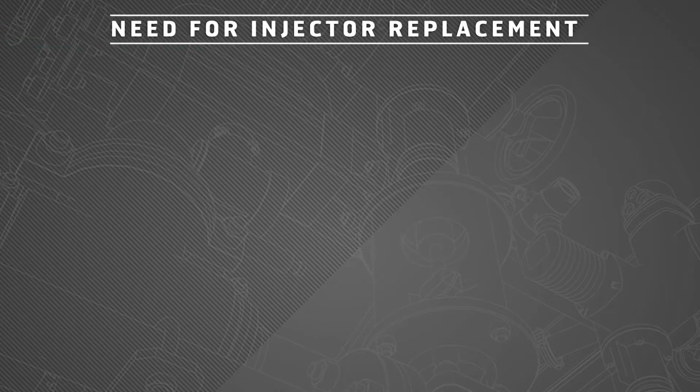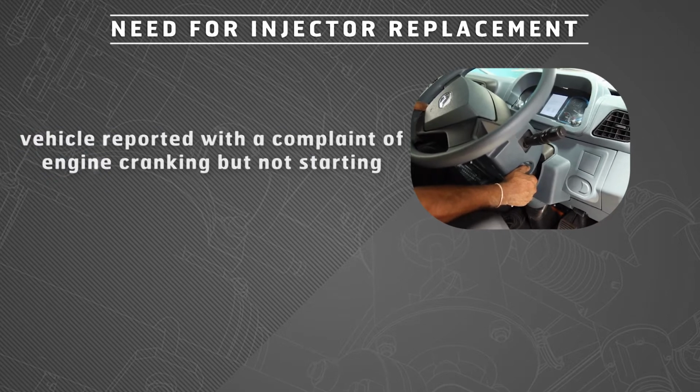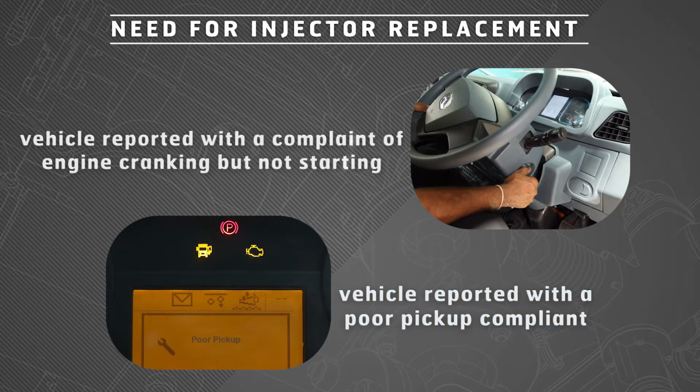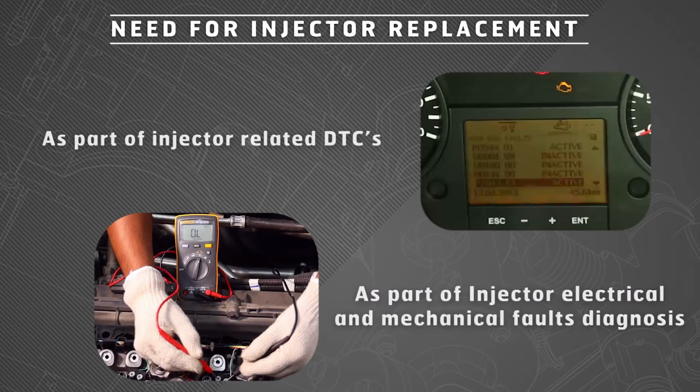Need for injector replacement as part of diagnosis for vehicle reported with a complaint of engine cranking but not starting, as part of diagnosis for vehicle reported with a poor pickup complaint, as part of injector related DTCs, as part of injector electrical and mechanical faults diagnosis.